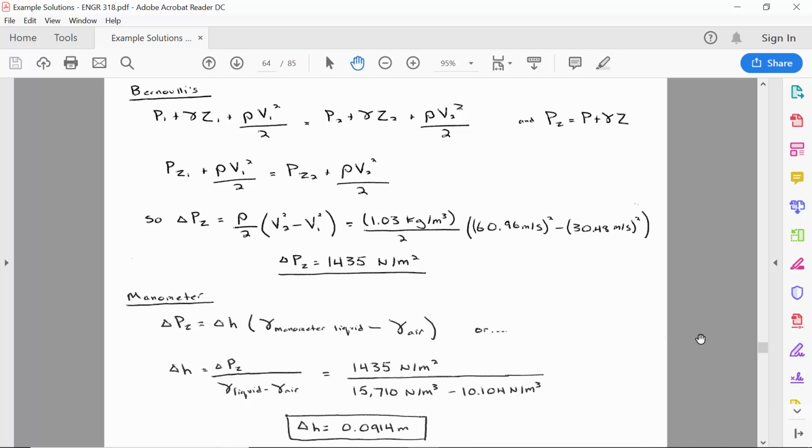So what is piezometric pressure again? It's like the change in pressure already accounting for the effects of the elevation difference. Because sometimes a pressure changes because a point is higher or lower, but this piezometric pressure is accounting for other factors, like in this case, the change in diameter and the increase in speed. So this piezometric pressure is telling us how much of that pressure is because of the decreasing diameter.